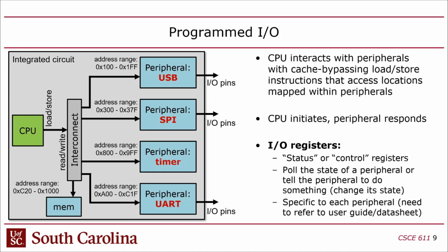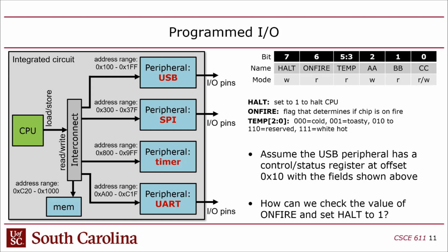So we talked about this notion of address ranges, I/O ranges. Make sure you're comfortable with this. There'll be at least one, I think two questions about this on the exam. Address ranges are basically ranges of addresses that you can use from the software to communicate with hardware. This is how all modern hardware machines do hardware-software communication, so this is really important. You'll see this come up a lot whenever you do bare metal programming.